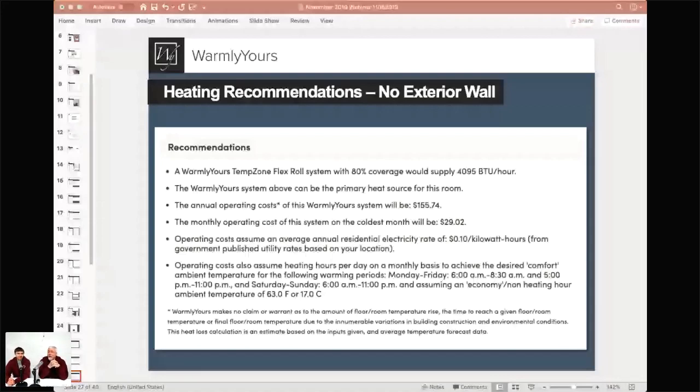But if you were doing this in a living room or a bedroom, let's pick a living room, if you don't have anything that's a box bottom sitting on the floor, you can ask for maximum coverage, which could get you anywhere between 4, 6, 8 inches from each wall. Normally we would say if you're not doing a room heat for primary heat source, we can pull off the edges a little bit and only put the heat where you walk.